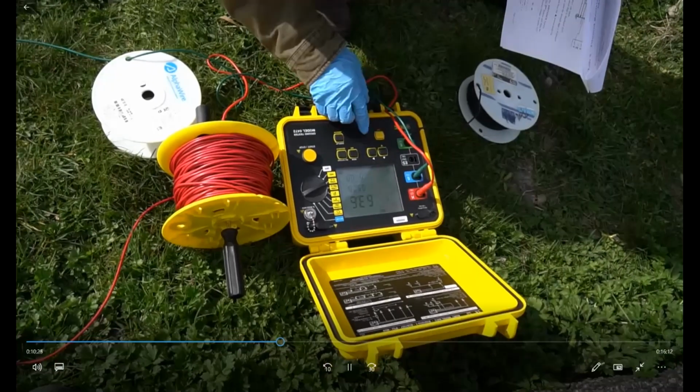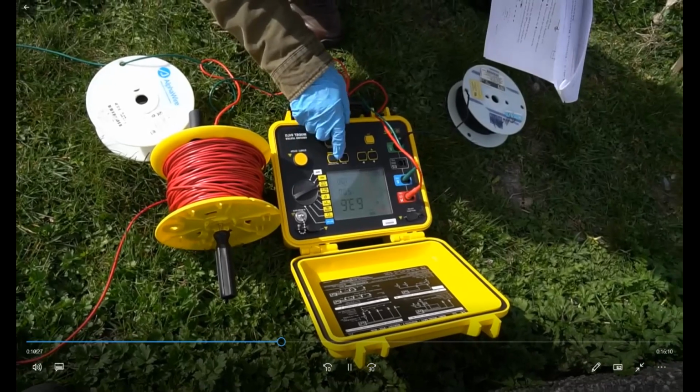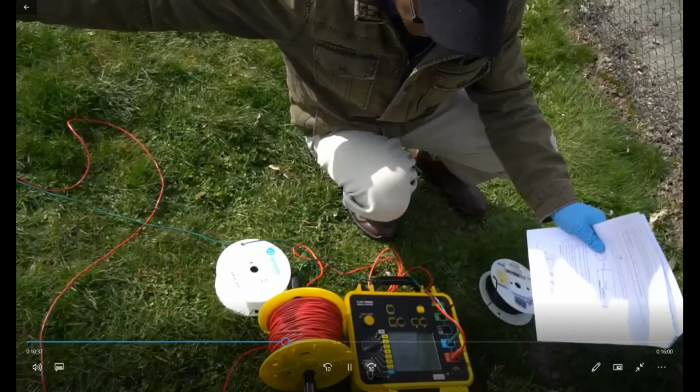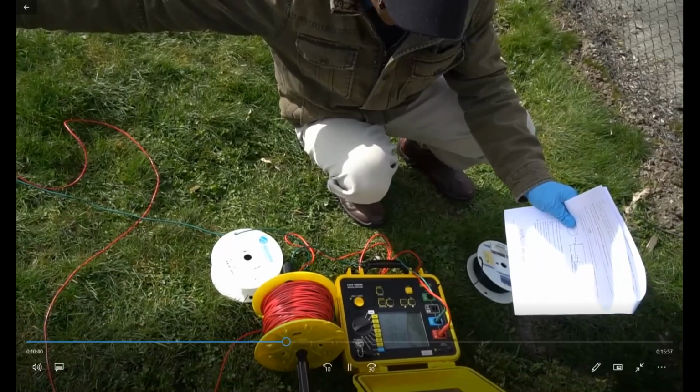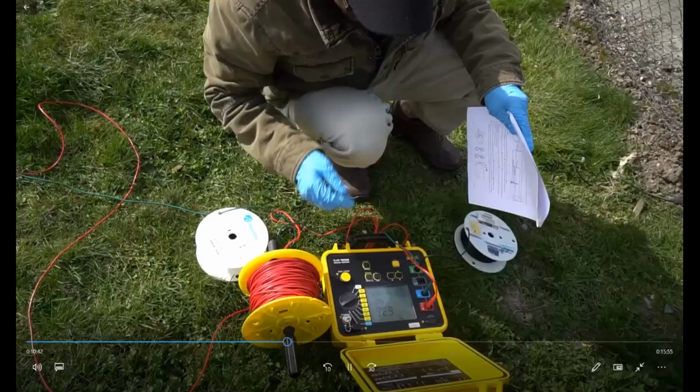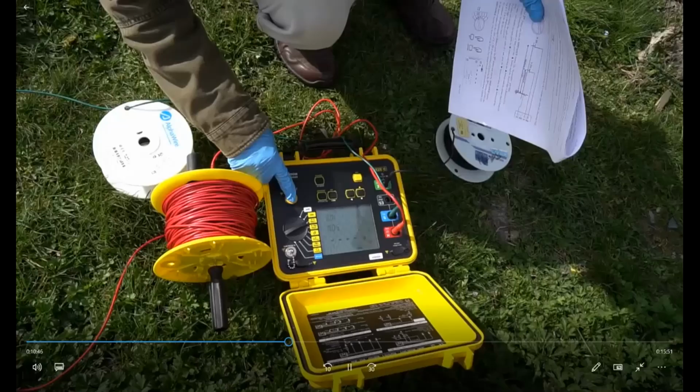We have 10 second distance again. So it is set up. Our main distance for current injection, 50 meters, is remaining the same, but D will get changed to 10 meters, and we physically also put the probe 10 meters away from this ground reference point. Now we'll take the measurement. We'll press the start button.